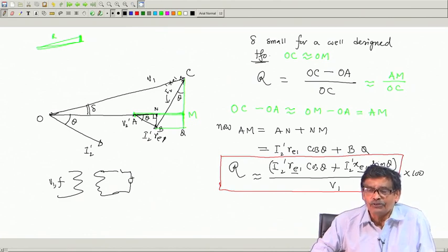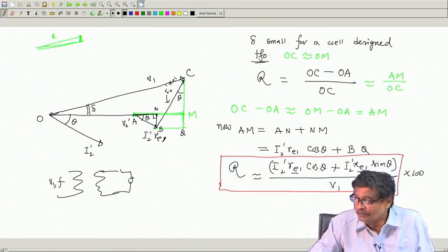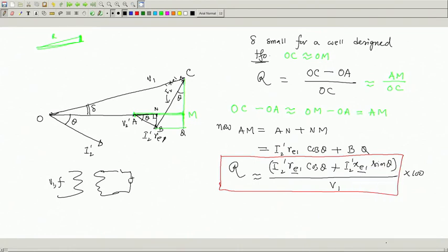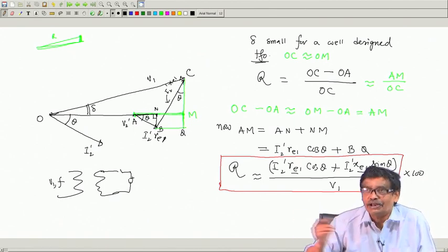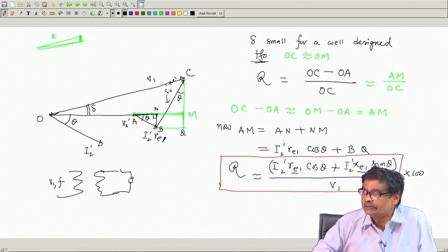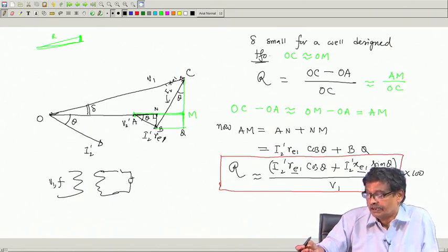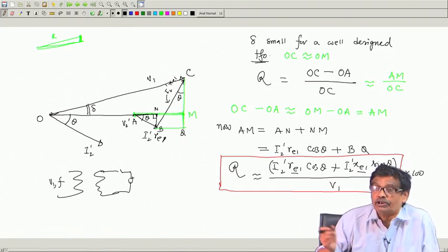Okay? Because open circuit and short circuit tests are very simple tests. I will carry them out and find these values, then tell me what load current the transformer is delivering, of course up to rated current, and at what power factor. You give me these two pieces of information, and I will be able to give you the value of regulation, how much the voltage will drop.